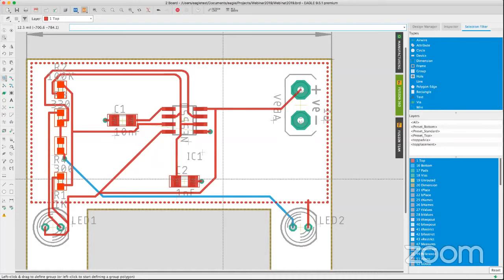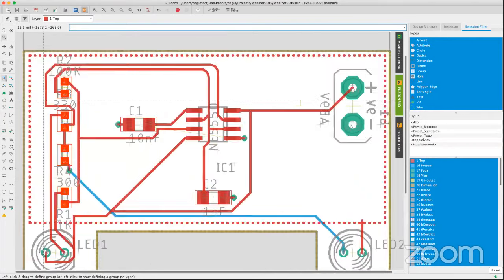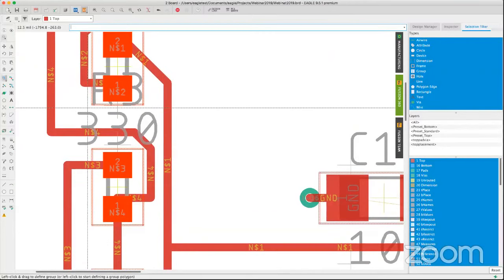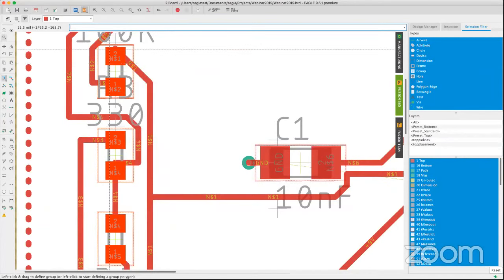So I have here a question: how to connect PCB connectors at equal distances of 5.08 millimeters. I don't think we could specify that. It just aligns them according to equal distance. Yeah, so the align command will look at which components are on the extremes. If you're going to distribute vertically, it takes the top part and the bottom part, calculates the distance between them, and then divides that by the number of items. Correct. So you can't specify it that way.